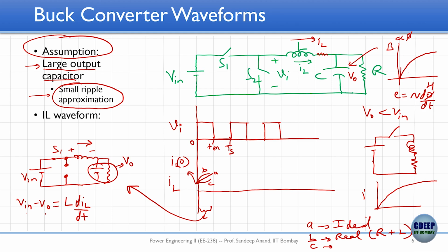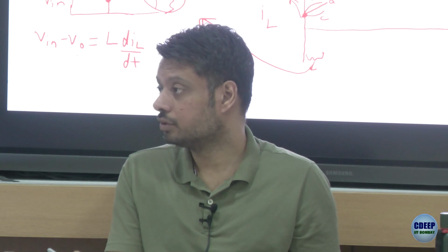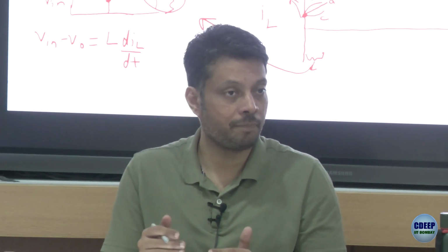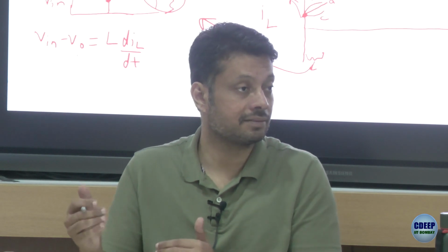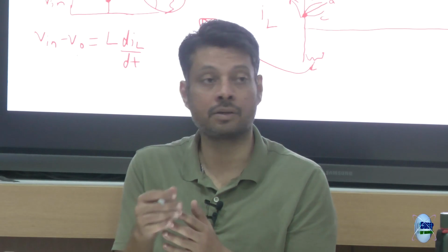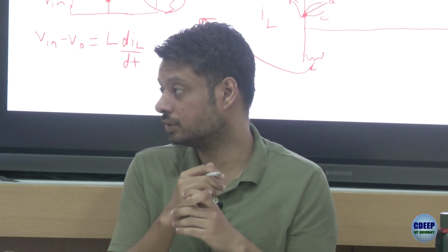So for each increase in flux, the initial increase in current will be small, but then the same increase in flux here would lead the increase in current to be very, very large, right? H is proportional to current. So initially you see some small slope, but then the slope will keep on rising. So you can have C if your core is a saturable core, right? That's a possibility.